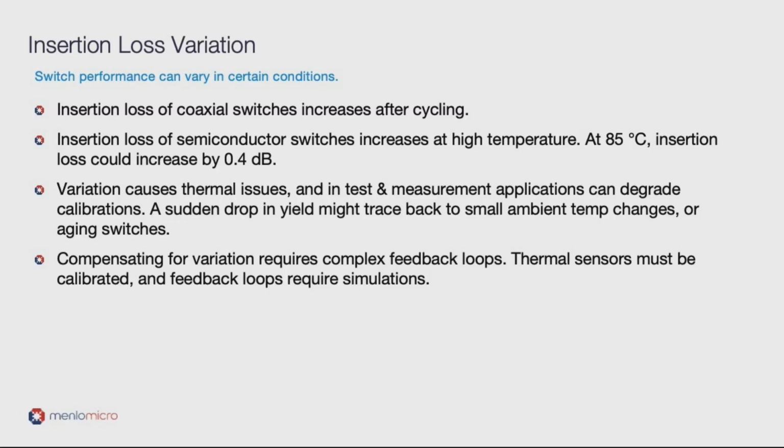On the other hand, semiconductor switches will be far more reliable cycle to cycle, but can have variation over temperature. So at 85 degrees, the insertion loss could increase by up to 0.4 dB. This could mean several extra watts of power dissipated in the switch when at higher temperatures.